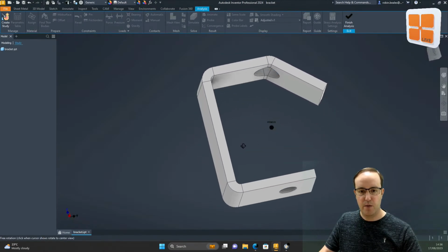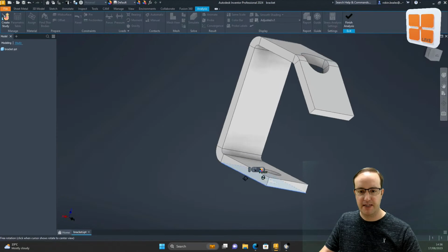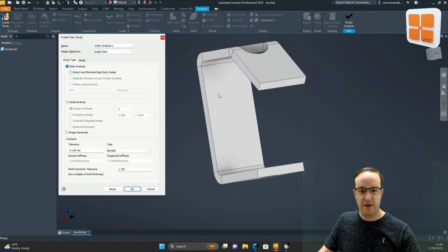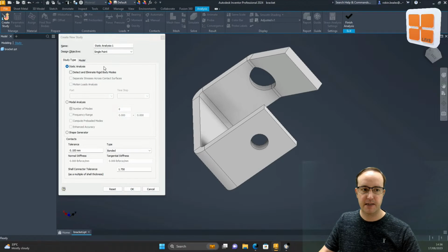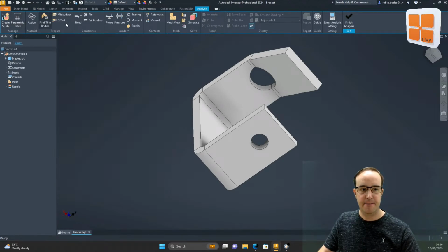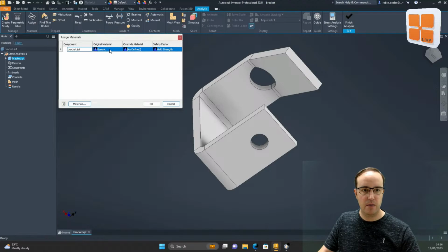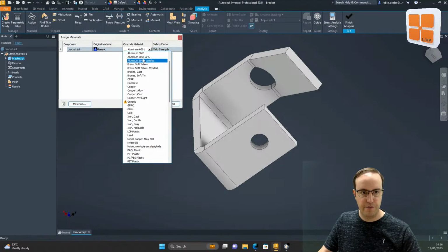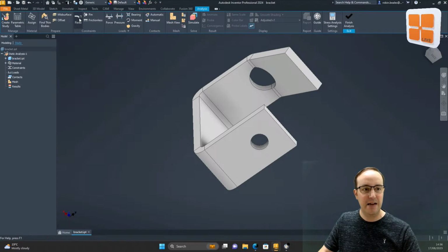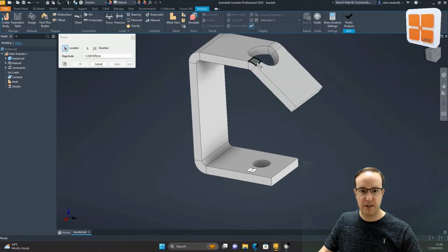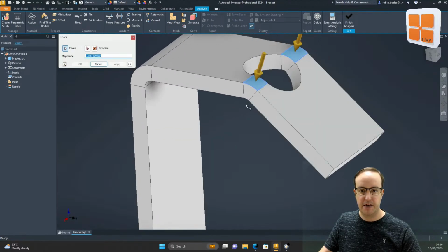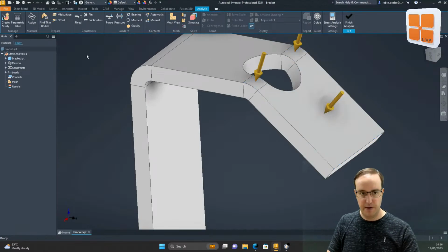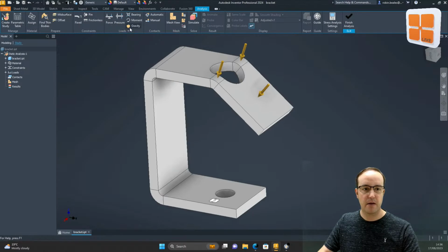We're going to say that this bracket is bolted to the desk on the underside, and I'm going to put a bit of weight on it for the purpose of this. So let's do a single static analysis. Let's create a material. We're just going to use an override material of aluminium. Hit OK. We're going to have a fixed constraint on the bottom here. I'm going to put a simple force on this radius at the top and on this face here. For the purpose of this, we've got 25 on there. Nothing too big. We've got a bit of gravity as well going in that direction.